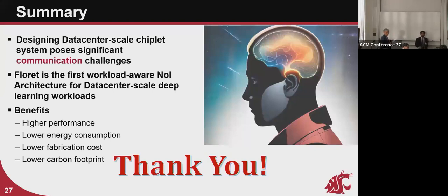You mentioned workload aware, right? So you are designing a different architecture for each mix of workloads? So this is one fixed architecture. The workload awareness comes from the contiguity that we are maintaining due to the Li to Li+1 nature. So it is agnostic to whatever CNN we might use, because all of the CNNs have that Li to Li+1 primarily. The skip connections travel through this NOI.